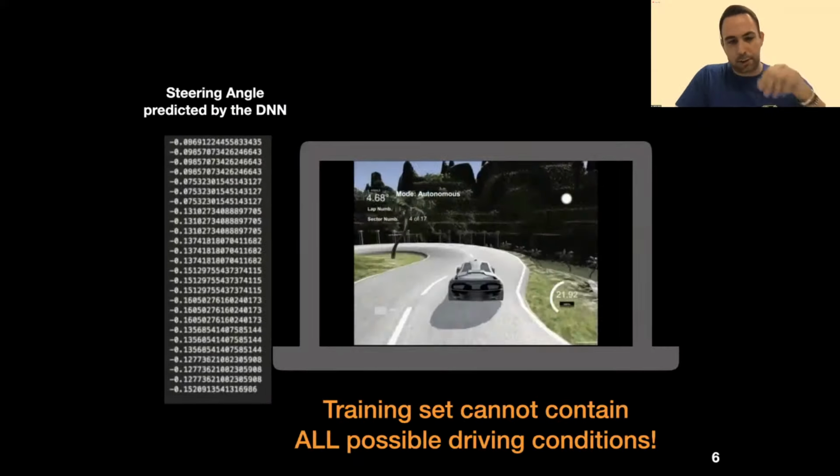As a core component of our technique, we rely on autoencoders, which are neural networks whose task is to reconstruct the input they are given with high fidelity, as measured by a distance metric such as the mean squared error. The rationale of using autoencoders for anomaly detection is that we can train them with the same data used for the driving models. Thus, the autoencoder will be able to reconstruct well inputs that are similar to the ones it was trained with, whereas it will fail to reconstruct inputs that are unseen, hence potentially unsupported by the car.